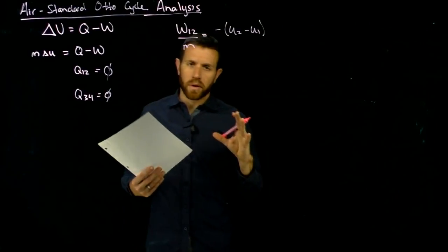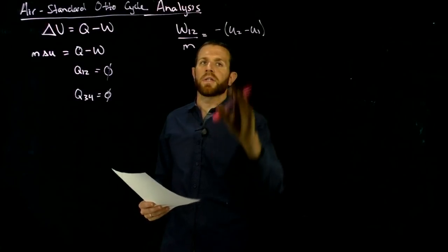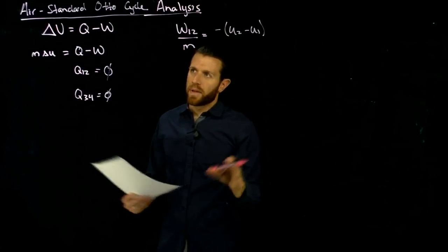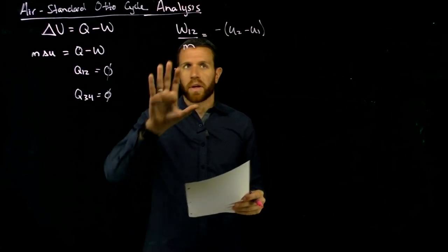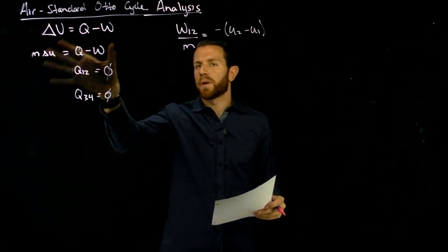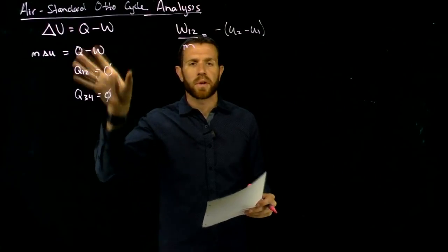Don't fall into the temptation of using enthalpy in this process analysis here. So again, we're using internal energy because that's what is coming from our first law energy balance.